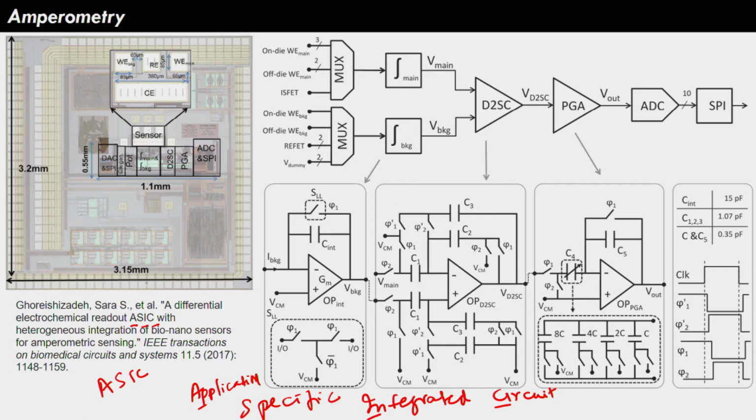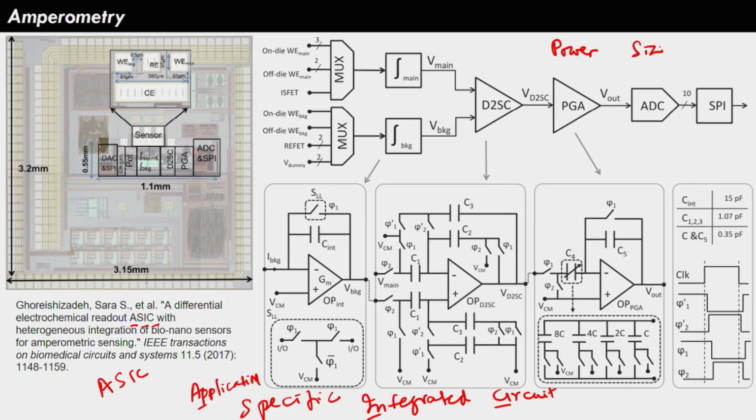Generally in wearable medical devices we have two trade-offs. Trade-off means we have to think of mainly two aspects that we need to look at. One is power and the other one is size. If your device is consuming a lot of power, that means you need a large battery on it, so your device size increases. Ideally we want something which is low power and small device size. This is where you can apply many clever techniques in your ASIC to ensure that your device is small size and low power consumption.